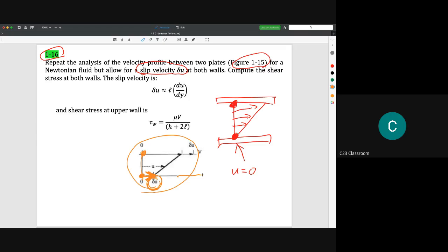Or we could engineer our surface. If you do more research, you will find that nowadays a nanoparticle coating reduces the no-slip condition. The molecules will flow on the nano coating, because the molecules cannot stand on the surface anymore, so they will not stick on this surface very well.